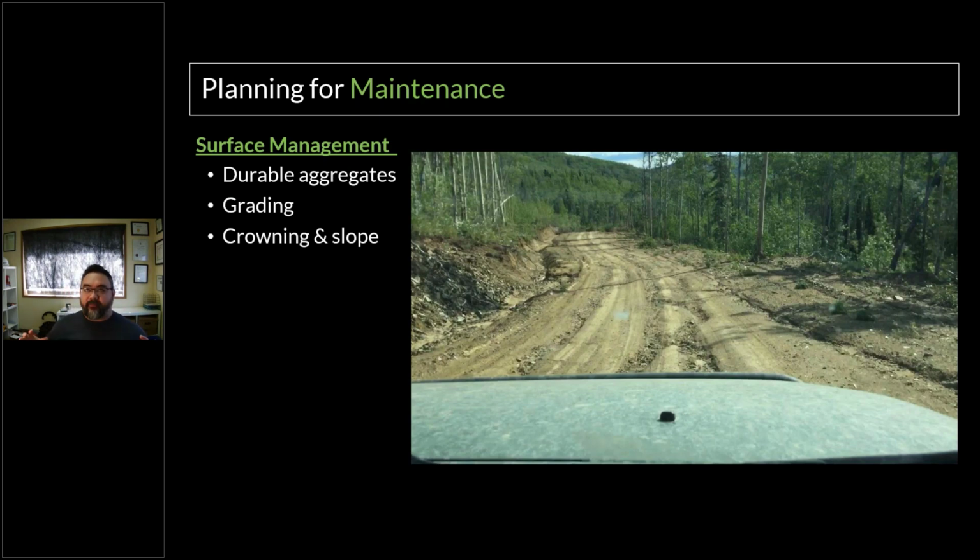Another important thing that I don't think we think about enough in the forest sector or in the resource sector is understanding things like the durability of the aggregate. So how strong is the aggregate in your surfacing, and then what will it weather into? Is it going to weather into sands, or is it going to weather into silts? But understanding gradation of surfacing and how that impacts stability.